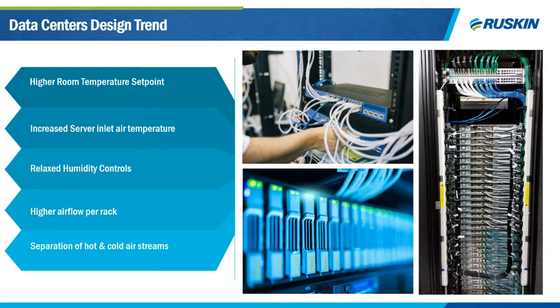All right, so we talked a little bit about the energy standards. We also talked about the push to reduce energy usage, yet at the same time we have a higher kW. So that's really a challenge. Now the good news is that these servers are manufactured to operate at a much higher temperature set point. They also have relaxed humidity controls.